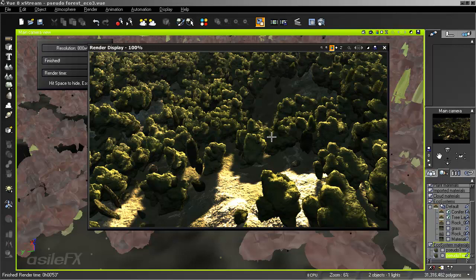The lighting is going to change if you switch over to ray tracing from shadow maps, and shadow maps kind of have some problems with animation. So depending on how you set it up, you might need to make a couple of modifications or set up multiple directional ray trace lights from slightly different angles, just 1 degree off, to kind of correct that.